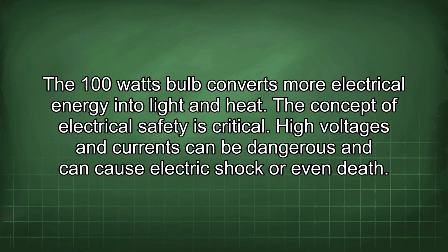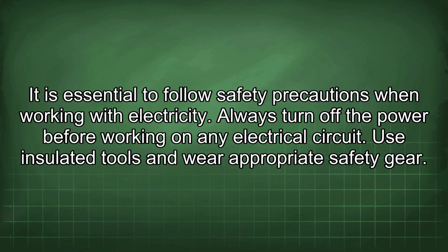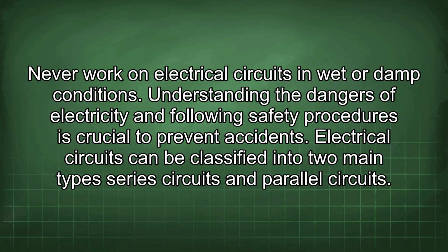The concept of electrical safety is critical. High voltages and currents can be dangerous and can cause electric shock or even death. It is essential to follow safety precautions when working with electricity. Always turn off the power before working on any electrical circuit. Use insulated tools and wear appropriate safety gear. Never work on electrical circuits in wet or damp conditions. Understanding the dangers of electricity and following safety procedures is crucial to prevent accidents.